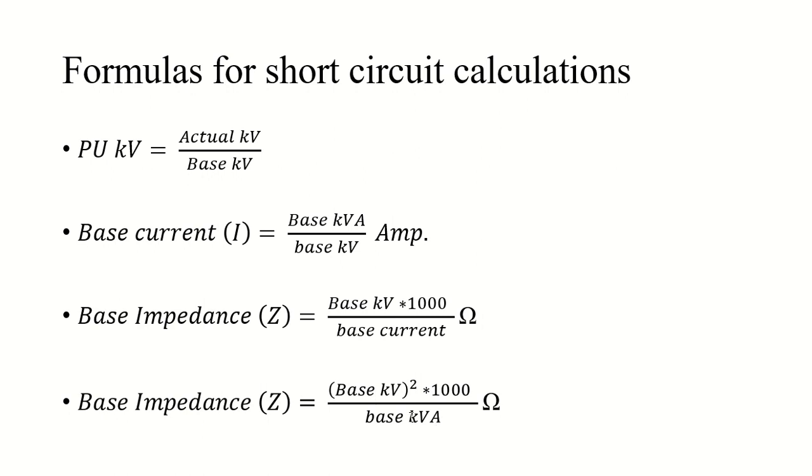So there is already a quantity in kilos present here, which was not in the previous formula of base impedance. And again, pay attention that both base impedance and base current have units, because these are base values. Base impedance has the unit ohm and base current has the unit ampere.